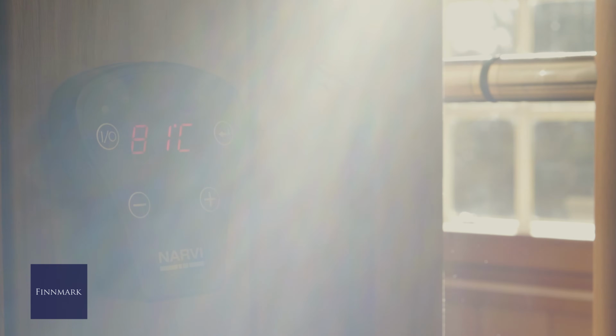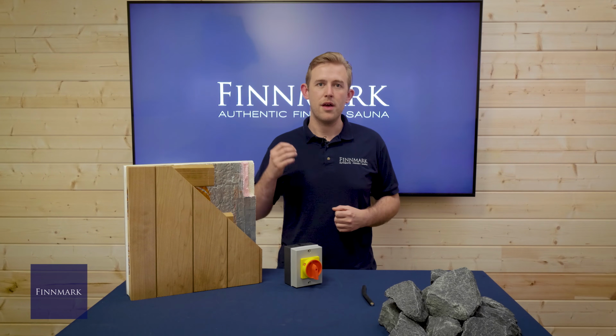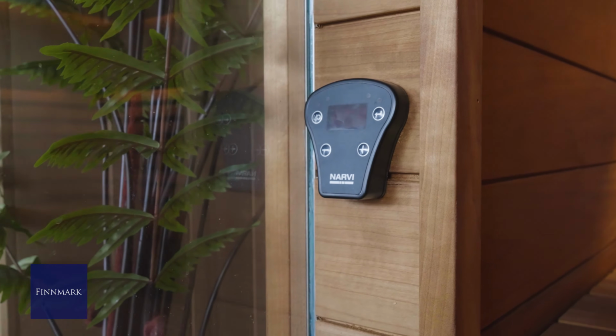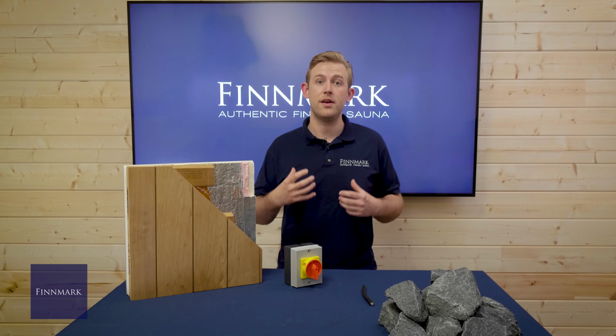Most sauna heaters have digital thermostats and control units, which need to be considered in terms of their location and where they're placed within the sauna. The thermostat will be specified by the heater manufacturer, but is often located on the wall above the heater at about 100 millimeters from the ceiling. Depending on the product, the controller can either be installed within the sauna, in the space adjacent, or in commercial applications in a plant room or safely secured behind an access panel. Not all heater controllers are suitable for inside the sauna, so you'll have to check that when you're specifying.